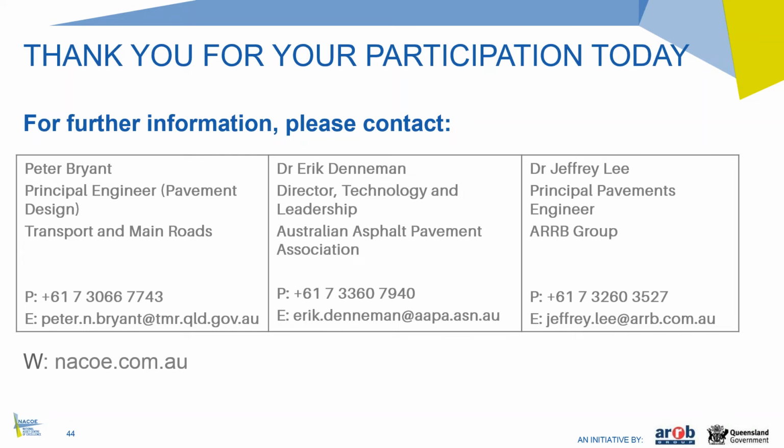Well, I think global warming is more a risk to ice on the poles than it is to asphalt. But in general, we're designing for 30 years. Asphalt increases in stiffness over time, so the modulus should go up, as long as there's no damage done. And the other side of that coin is that as the temperature goes up, we would actually expect the fatigue performance of the material to improve. So I wouldn't be too concerned about that if we're only looking at the technical aspects of it. I'm very concerned about global warming, but not for our asphalt items.